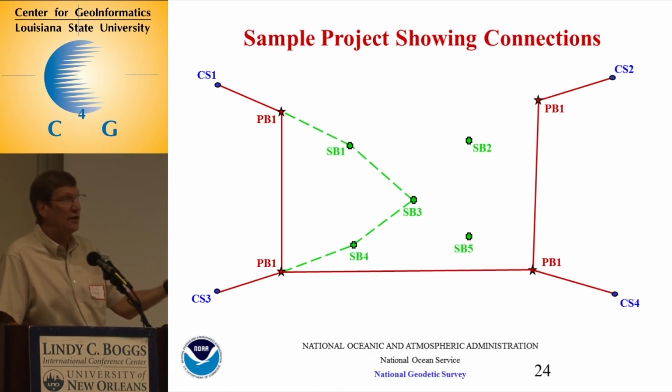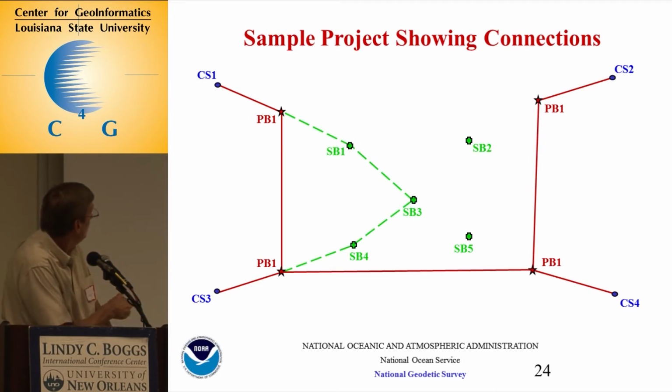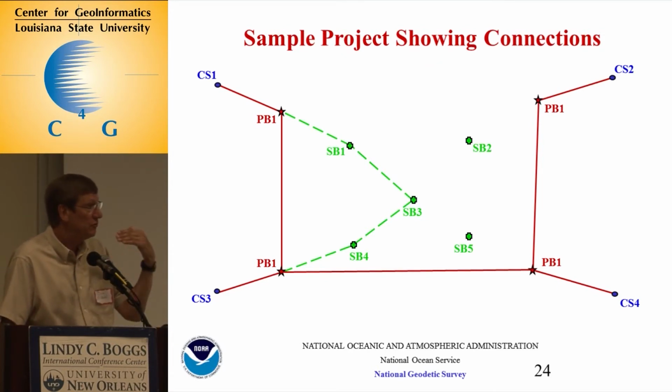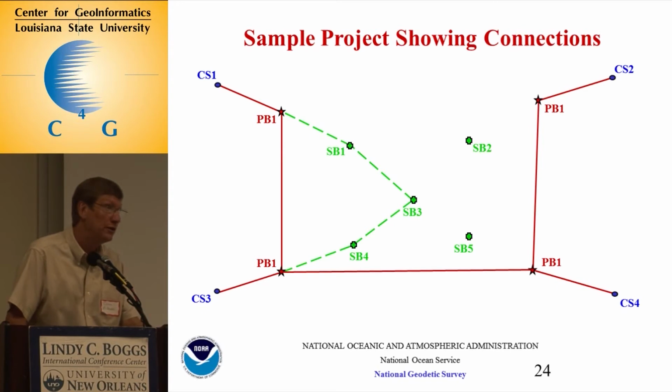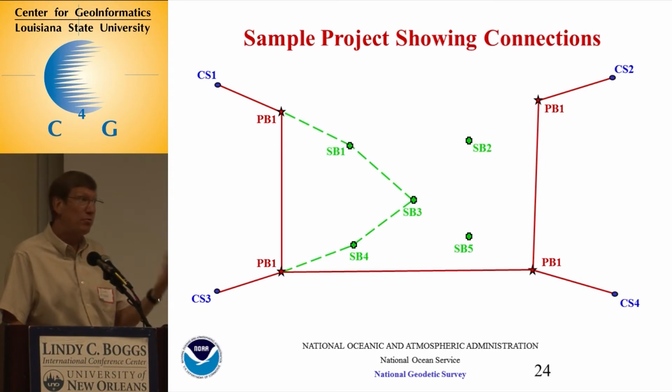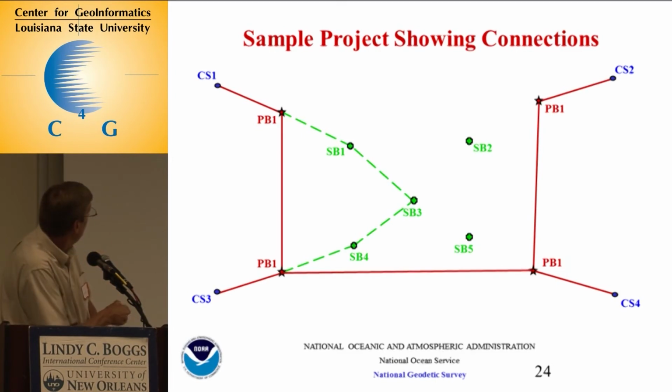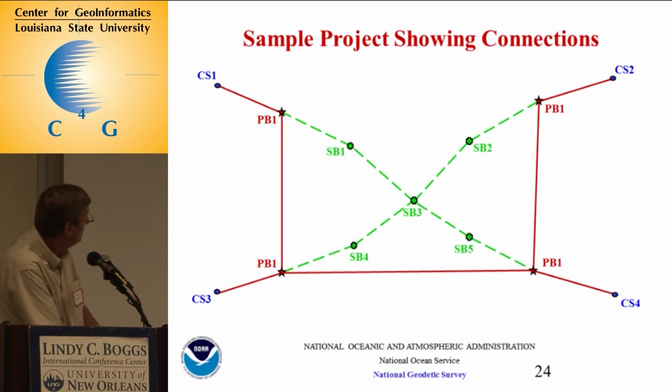Now, I did a lot of leveling data analysis, and I'm telling you what, in a lot of leveling, you could have great misclosures here, here, here, and here. By the time you check in there, you could be out because you have some small systematic effect in your procedure or processing. So that's where some of these guidelines also came from. I'm thinking of this just like a level network, and saying, hey, if you can't detect this error or reduce it individually, then you need to have this network. Then you do the same connection going back on the other side, so you have that connection.